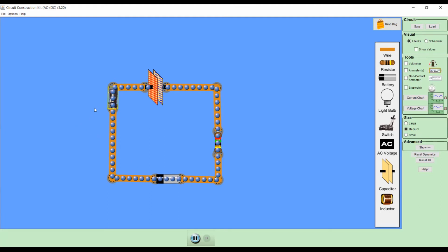The current was flowing quickly and now you don't see how the current is flowing, because the capacitor has probably almost got charged. Because if you multiply 25 by 0.2, you get 5 seconds. 5 seconds is the RC time constant for the capacitor in our circuit.